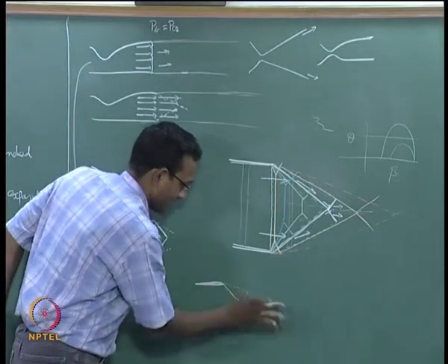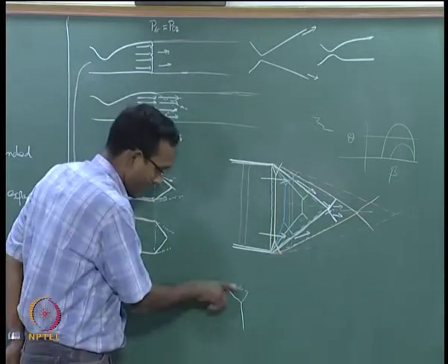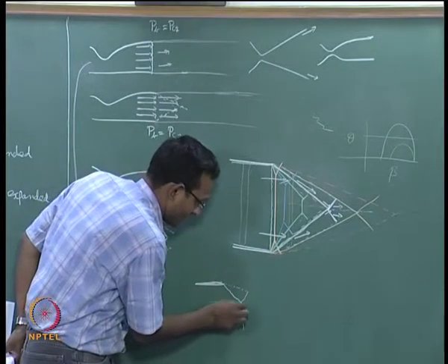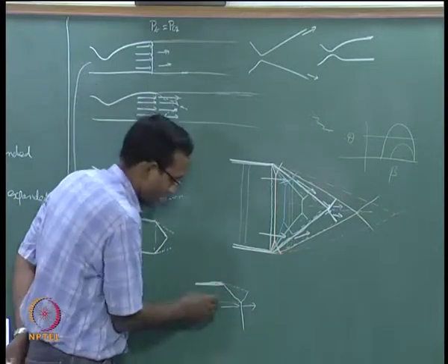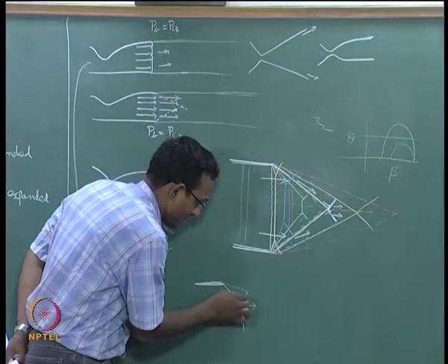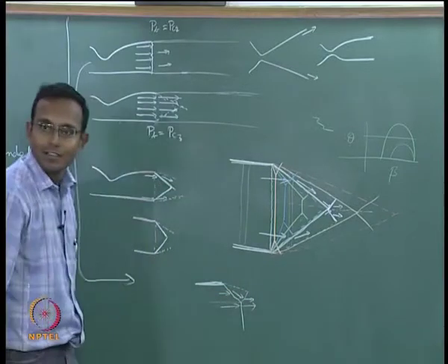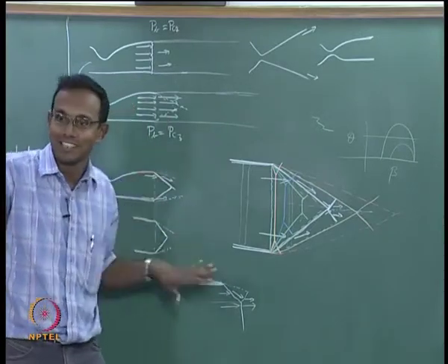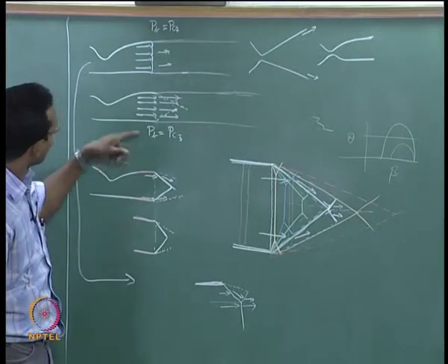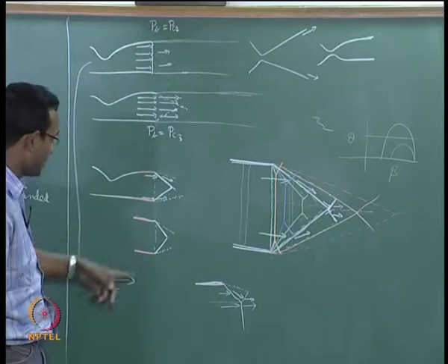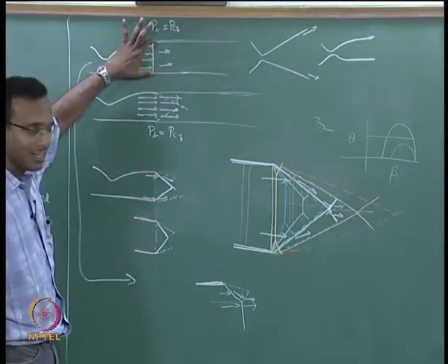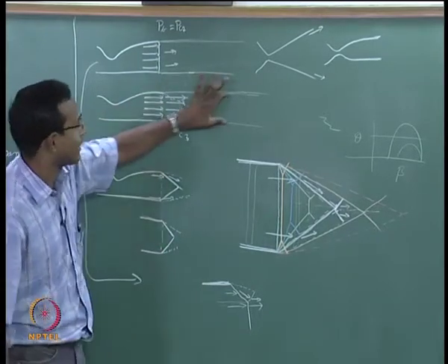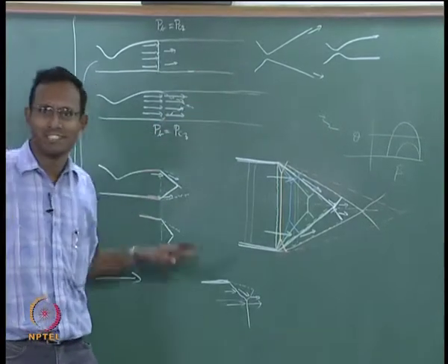I will erase the extra things. Okay. And below this line fluid is just seeing a normal shock, it just jumps like a normal shock. The remaining regions is going to come straight, turn like this and go like this. If you see this beauty of nature being symmetric or very continuous, all that is seen here. When we discussed before, looking at all these pictures, we said that it was going straight, suddenly it went to shrinking too much and then it shrinks lesser and lesser, becoming parallel again. That never happens in nature, nature is never discontinuous.